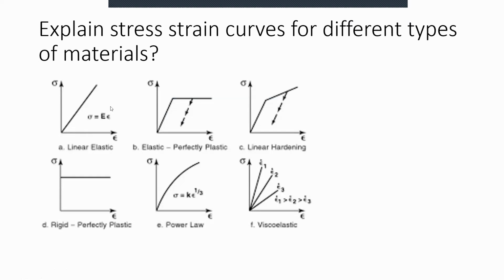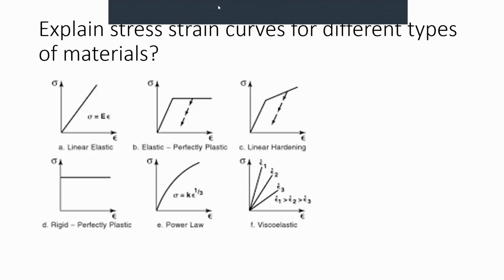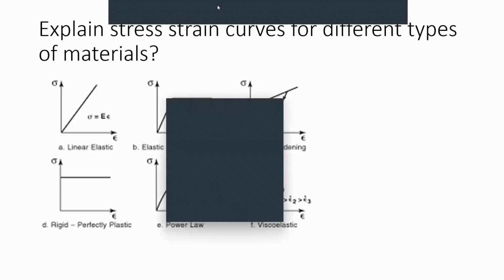This is the curve for a linearly elastic material. However, the proportionality limit is followed by the elastic limit, where the material is still elastic. Once you deform it, the material comes back to its initial dimensions. However, Hooke's law is not followed for that particular part. The material regains its shape, but not proportionally.